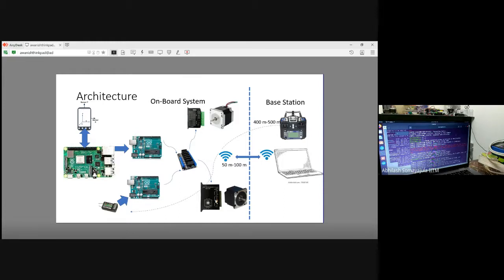Yes, but once the drive understands that, it generates the signal accordingly. When we say we are generating PWM, it doesn't go straight to the motor. It converts it into a trapezoidal or sinusoidal form, whatever it understands.